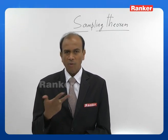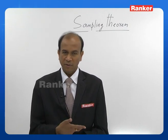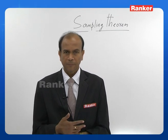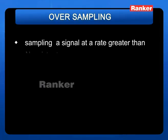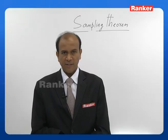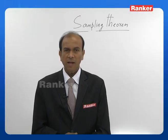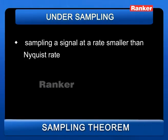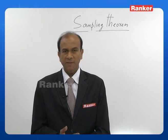And there are two types here, oversampling and undersampling. We have been using those words very frequently. What is oversampling and what is undersampling? Oversampling is sampling a signal at a rate greater than the Nyquist rate, that is fs is greater than 2 fm. Undersampling is sampling a signal at a rate smaller than the Nyquist rate, that is fs is less than 2 fm.